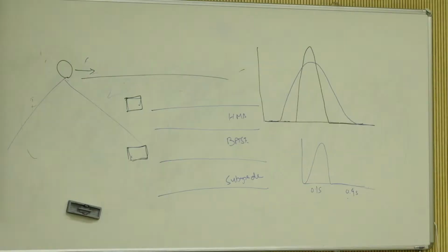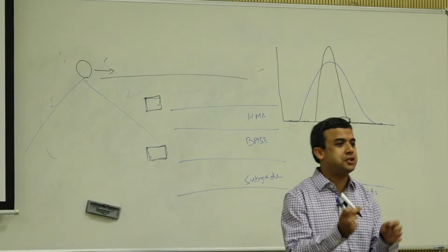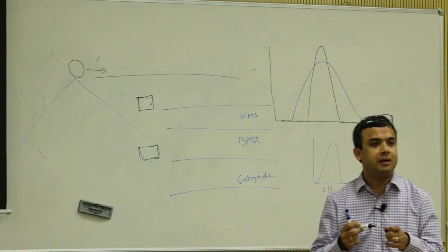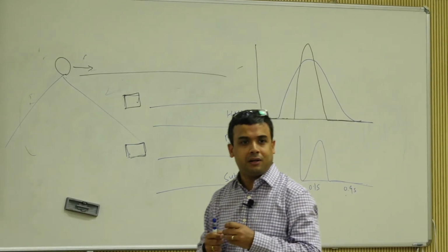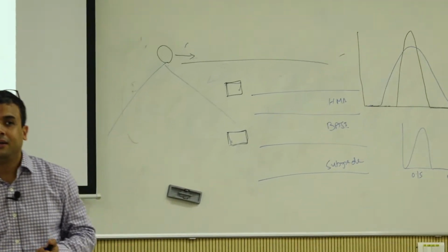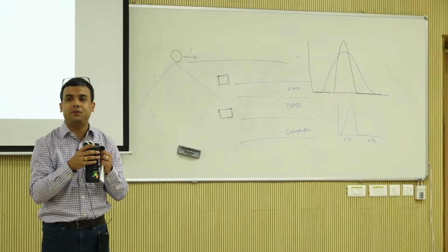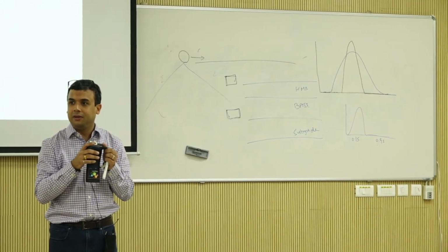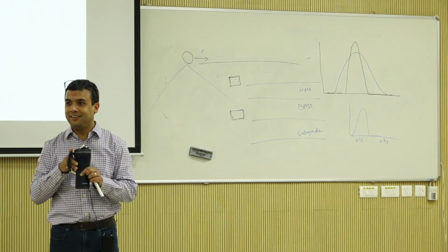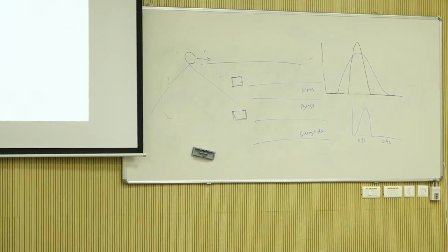Asphalt layer? No, you don't run a resilient modulus test on asphalt. I'm talking about AASHTO T307, which is like the actual testing that we did in the lab. For granular, have you done subgrade testing? How many of you have done aggregate versus subgrade? You have done aggregate, I know that. How many of you have done subgrade soils? What do you do? So one of you is wrong, right? The code says the same, so that's our excuse, isn't it?